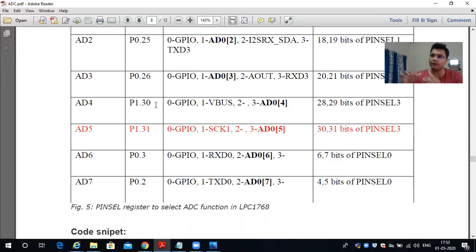In some proportion, we have to convert it into its equivalent analog voltage, and that analog voltage should feed into any one of these ADC channels. Then it will convert it into its equivalent digital 12-bit approximate digital value. That digital value then further needs to be processed. We will see how we will process it.